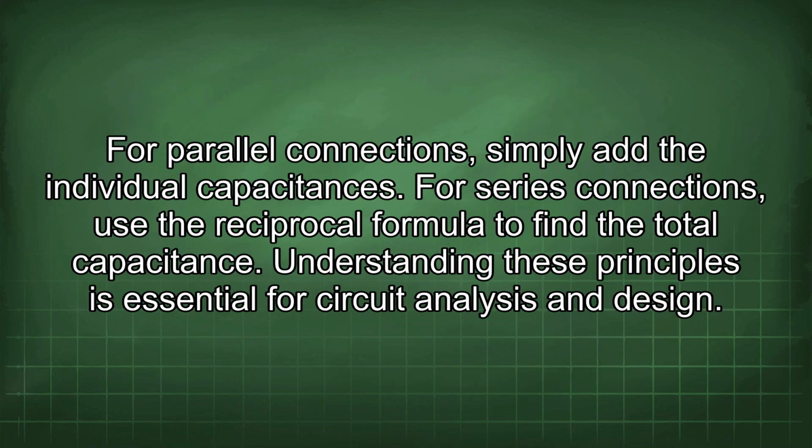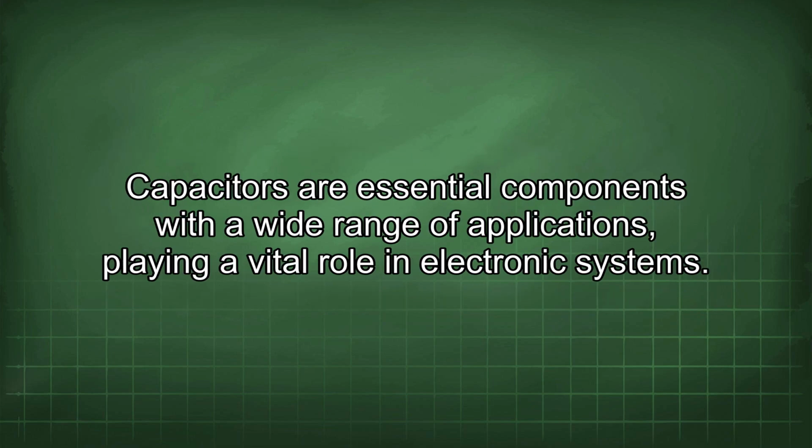For parallel connections, simply add the individual capacitances. For series connections, use the reciprocal formula to find the total capacitance. Understanding these principles is essential for circuit analysis and design. Capacitors are essential components with a wide range of applications, playing a vital role in electronic systems.